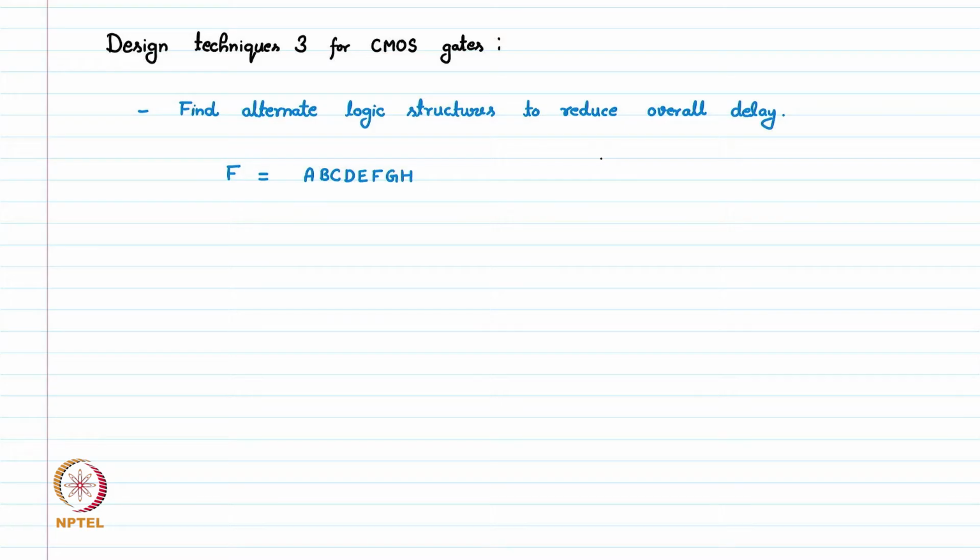So, I make a NAND gate, it is going to be a big NAND gate, which has 8 inputs, and because this is a NAND gate and we are calculating AND, we will invert the logic after this using a small inverter.